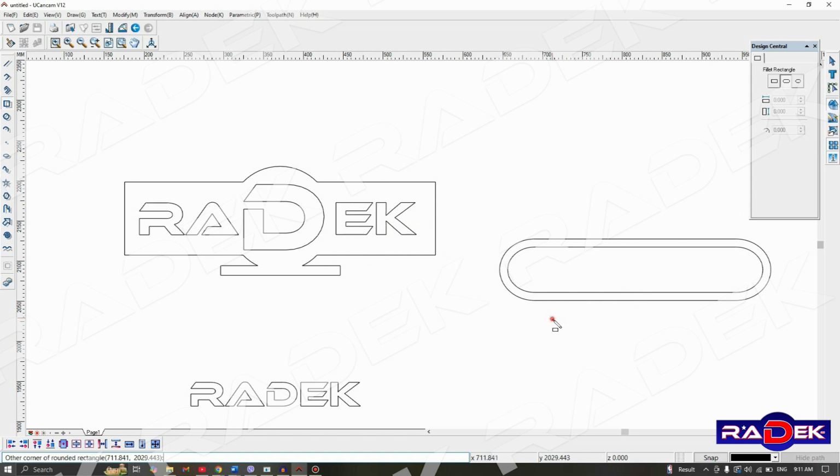Speaking of which, I need to draw the grooved section in the stand. I'll draw a rectangle and assign its dimensions. In our case it will be 150 millimeters length and 15 millimeters width. Our material has a thickness of 18 millimeters, but I plan to lower the thickness of the sign by 3 millimeters with one of the operations, which will make the sign 15 millimeters thick.